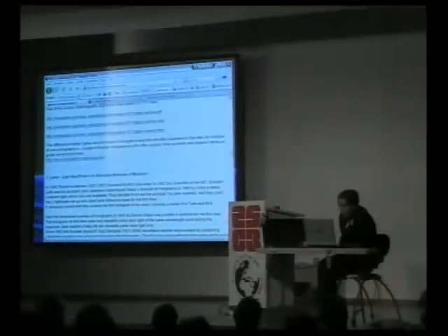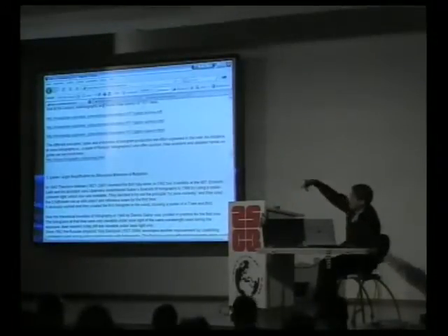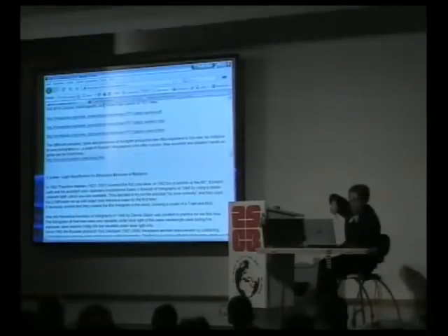A vibration inside of that system during the exposure of a fourth of that, which is 125 nanometers, in a room, this is nothing. This is like half a degree temperature difference between there and here. Speaking, no chance. No speaking during exposure.